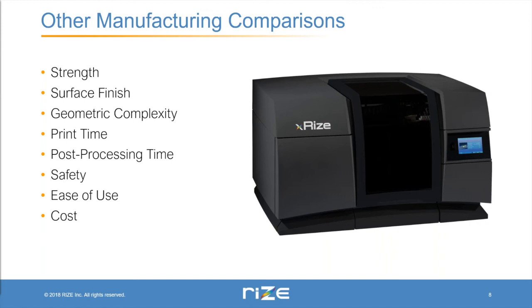So strength is very material dependent. You'll find that technologies that can produce parts in metal are of course going to have the highest strength. Beyond that, it's really what sorts of materials can be processed effectively with the different methods. So you'll find that fused filament fabrication can create quite strong parts.